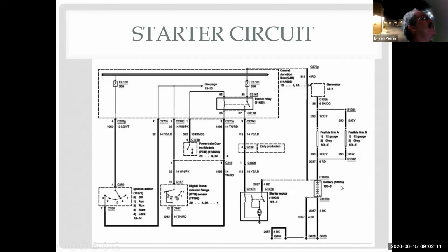I mean, look at all this stuff. I could have a bad battery connection. I could have a bad battery. I could have a bad connection in this wire at the starter. I could have a bad starter and solenoid. Oh, I could have a bad starter relay. I could have a blown fuse here. I could have a PCM that doesn't want me to start the car because it doesn't like my key today.